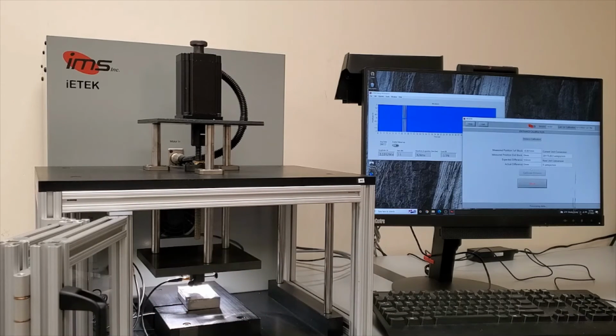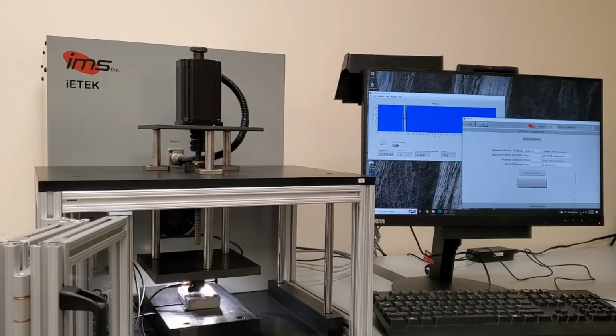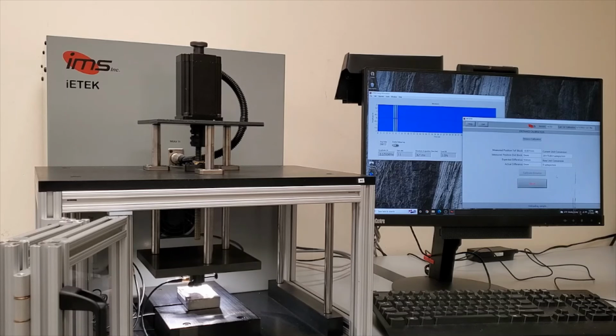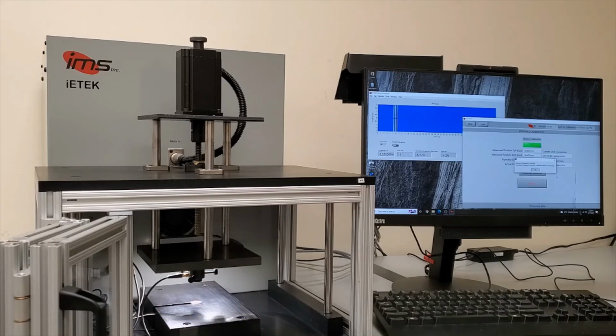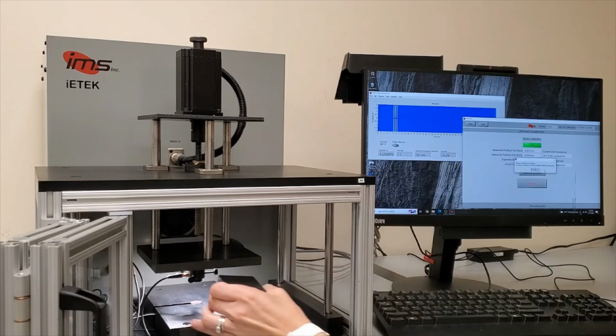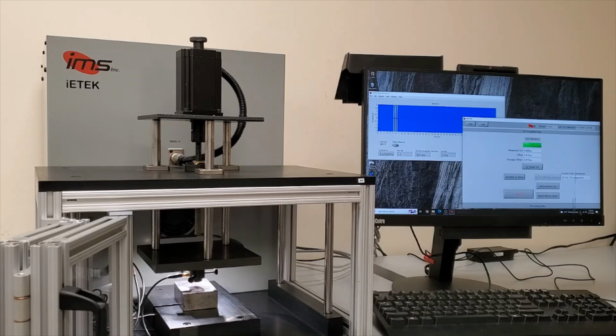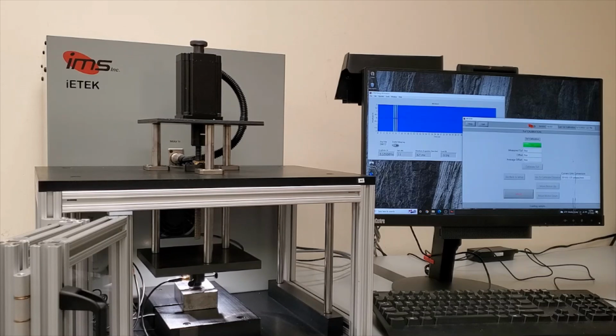Now, to do the distance calibration, what you need to do is choose the thinner distance calibration block, set that between the two transducers, and initiate the distance calibration measurement. The platform will come down and measure the distance between the two transducers. Once it does that, it will compare the two distances and generate, if it's within tolerance, a pass-fail indication. And as I mentioned before, after you've done the thin calibration, you will have to go back, as the final step, to the 1-inch calibration block and do a remeasurement. I think the menu has words on it that tells you exactly what the procedure is for doing all of the manipulations of the sample. Once that's done, the new calibration